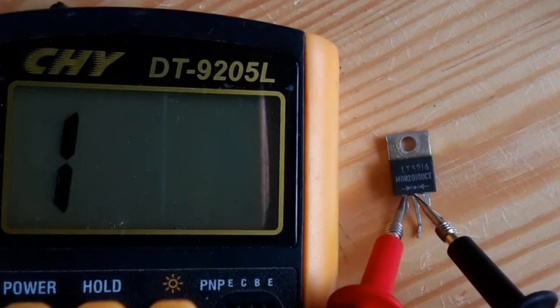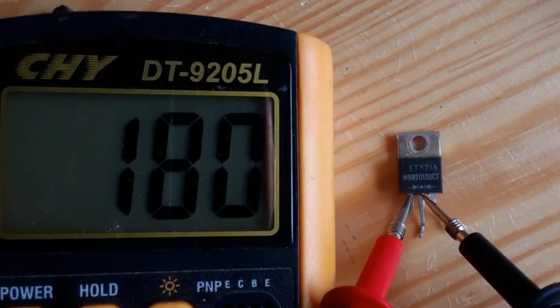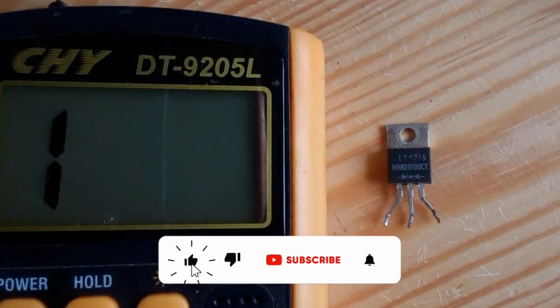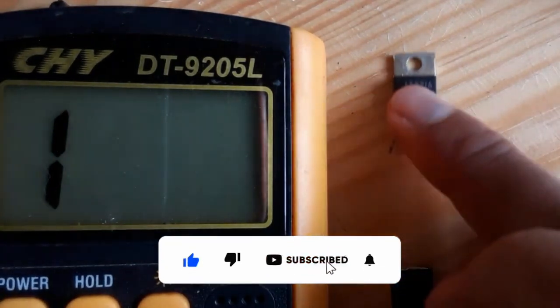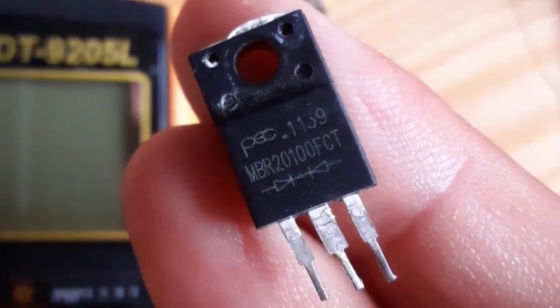Here we have the second diode. This is a good Schottky diode. This is how you can test it. If you get any buzzer or any continuity, it means failed. Automatically you should change it. Let's check this also. We have another one with the same working principle.